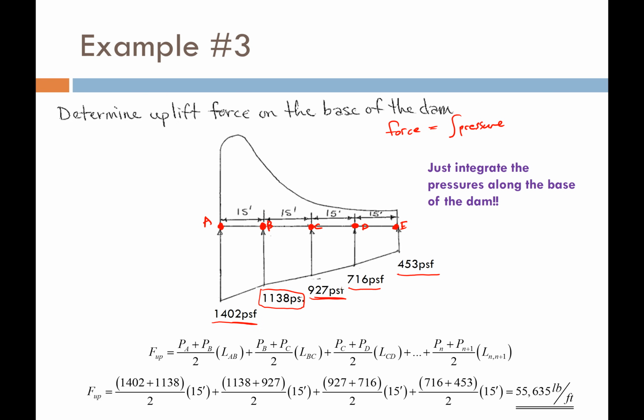I can use a basic integration technique like Simpson's rule or the trapezoidal rule to approximate the integration of the pressure on the bottom of this dam.